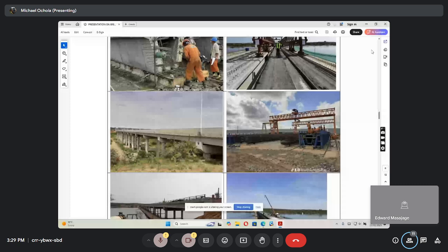So the pier supports are taking just vertical loads, not moments, right? No, not moment. Moment can also be transferred in a way. You have to know the wind, there is a tractive or braking force from vehicle, all transferred onto the pier support system. But of course, when you're using bearing, it is only vertical, but not only purely vertical. You must also subject it to even earthquake. This area was also checked for earthquake.